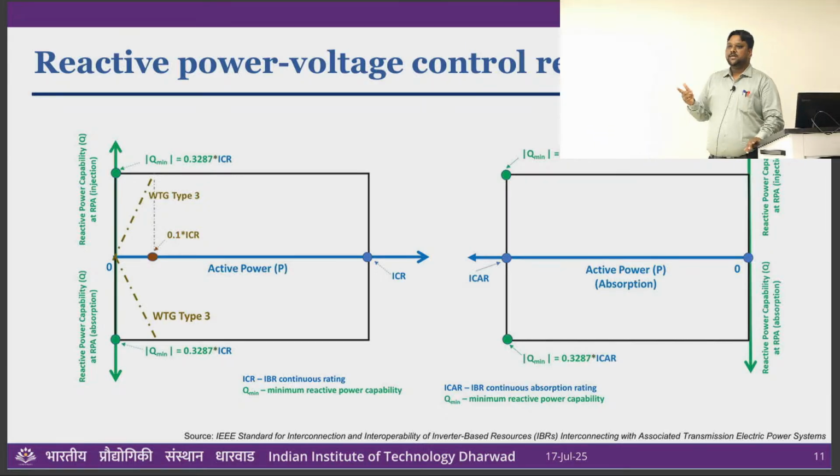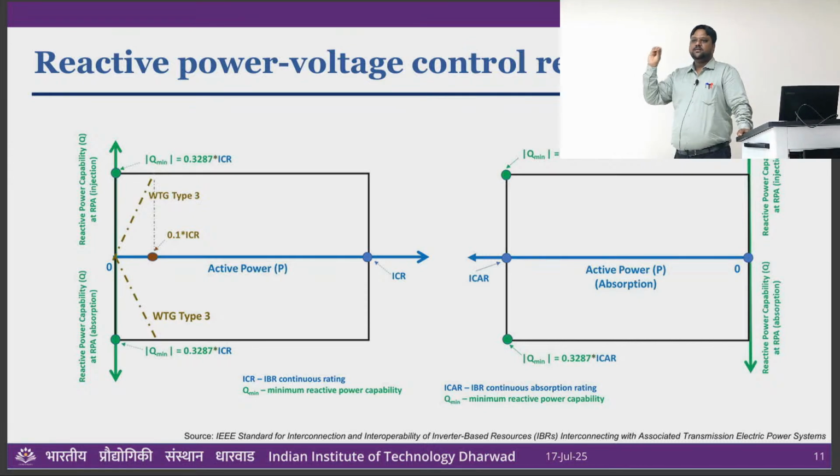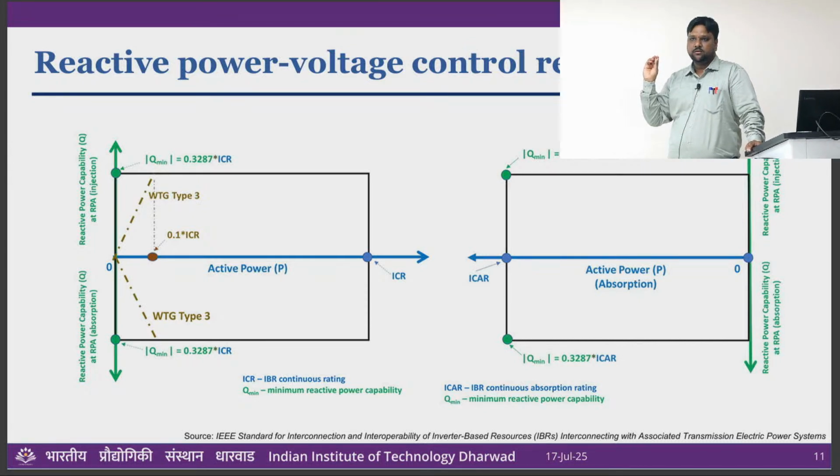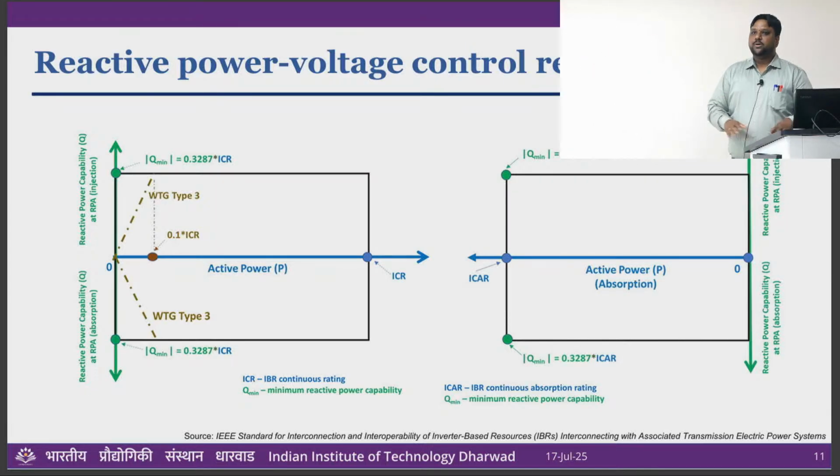So you have to maintain PQ first, that is the first point of check whether you are capable of connecting to the grid or not, because transient disturbances and faults are very momentary. You have to stay connected with the grid for all kinds of steady state zones. You can find more exact details in the document. I just tell you that this is how they see your power plant performance before connecting to the grid.